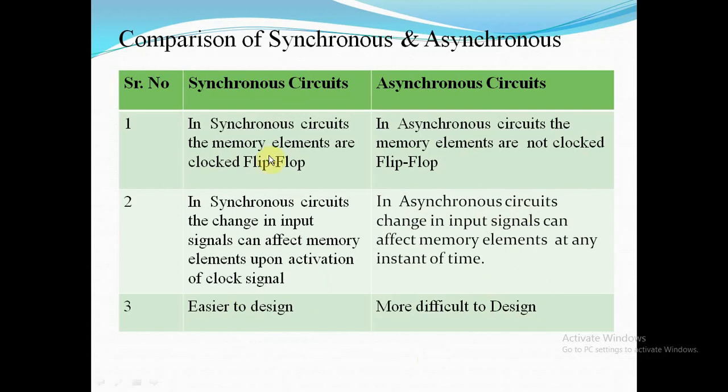In a synchronous sequential circuit, the memory unit used is the clocked flip-flop. Complexity: it is easy to design. On the other hand, in asynchronous circuits, the presence of feedback among the logic gates causes instability issues in making the design. Synchronous circuits are used in counters, different shift registers, and memory units. Asynchronous circuits are used in low power as well as high speed operations such as simple microprocessors, DSP, that is digital signal processing units, and in some communication systems for email applications, internet access and networking.